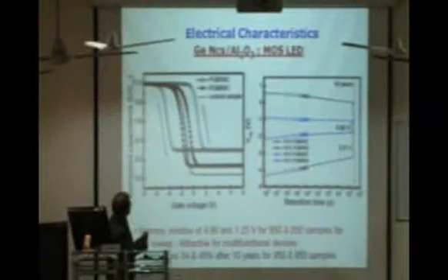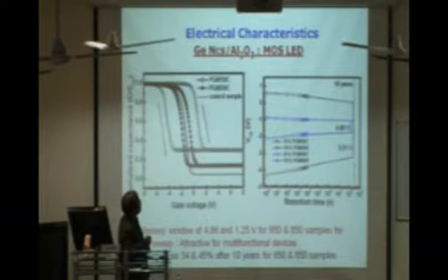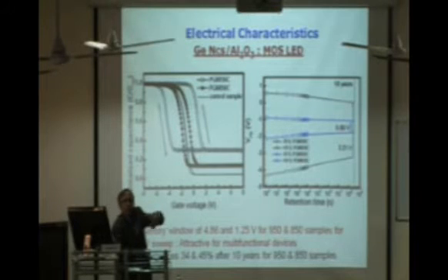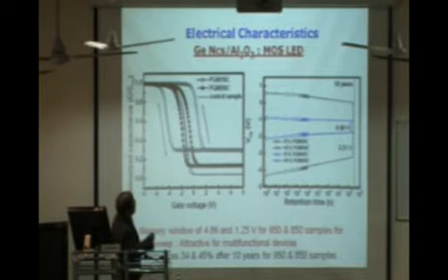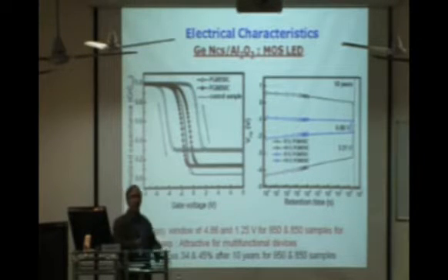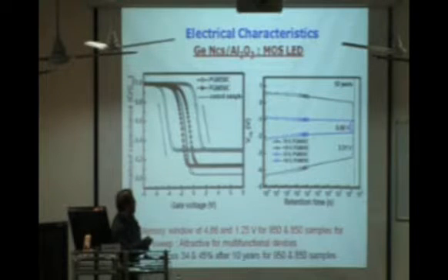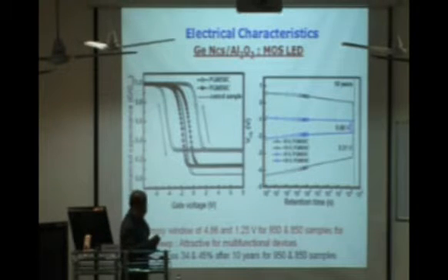And ultimately, for the device people, you have to show that ideally this charge should not leak, because this quantum dot is embedded in a very good insulator, this charge should never leak. But as you know, there are always some defects in the insulators. So since there is a little bit of defect in the insulators, this threshold voltage comes down as a function of time. And in fact, we do the measurements up to 10 to the 4th cycles and extrapolate up to about 10 to the 8 cycles, and we still see a good hysteresis width, so that it shows that this can be usable. In fact, a lot of companies are now making silicon-based nanocrystal memory.